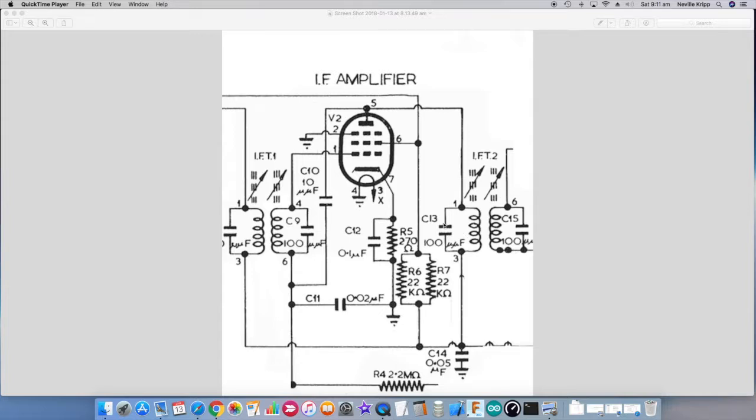And if we take a look at it, this tank circuit or tuned circuit here would be the tuned circuit that is in the plate or the anode circuit of the mixing valve. So in effect it's our first IF filter because it's tuned to the actual IF frequency. You'll note that coil is part of an air core transformer, and the secondary is another tuned circuit.